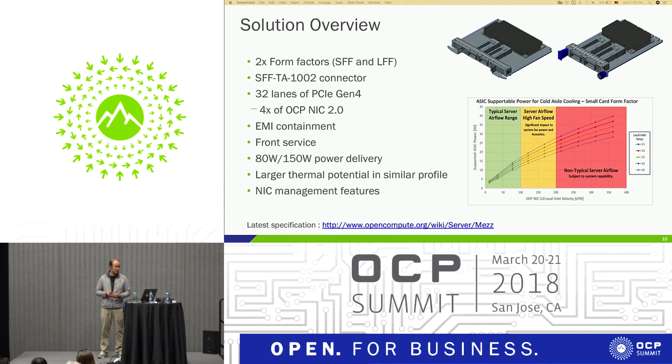And we also design in the EMI containment, since many OEMs are interested in this solution. And power envelope-wise, we have a much bigger power envelope from the power delivery point of view, although thermal is another challenge that Yueming will get into. We put quite a lot of work into the NIC management feature, and Hamel from Broadcom led the effort and put together section 4 of the whole management section in a much more professional way than what I did in 2.0.